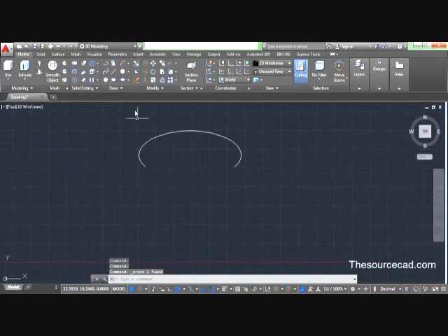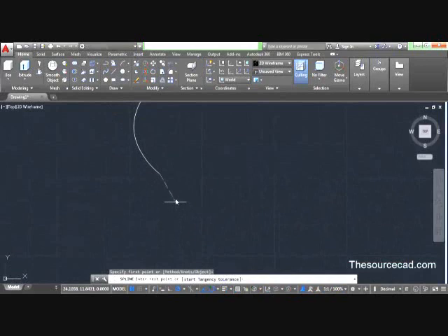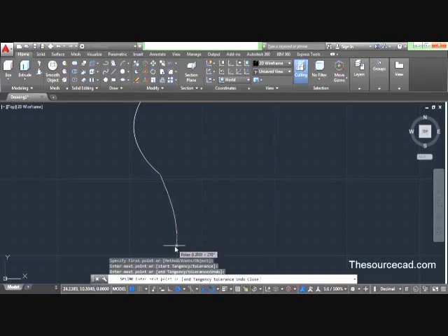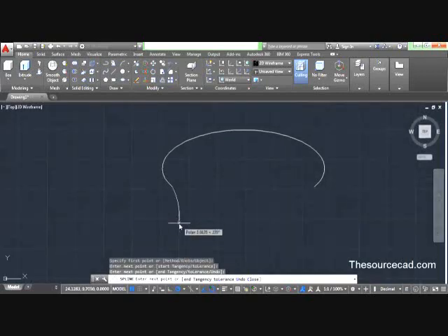Okay, so now we need to manipulate this ellipse. So go to spline and add a spline, starting from this corner point. Take a look at the geometry which I am making right now and try to make your geometry similar to this one. Okay, so here we have this line.